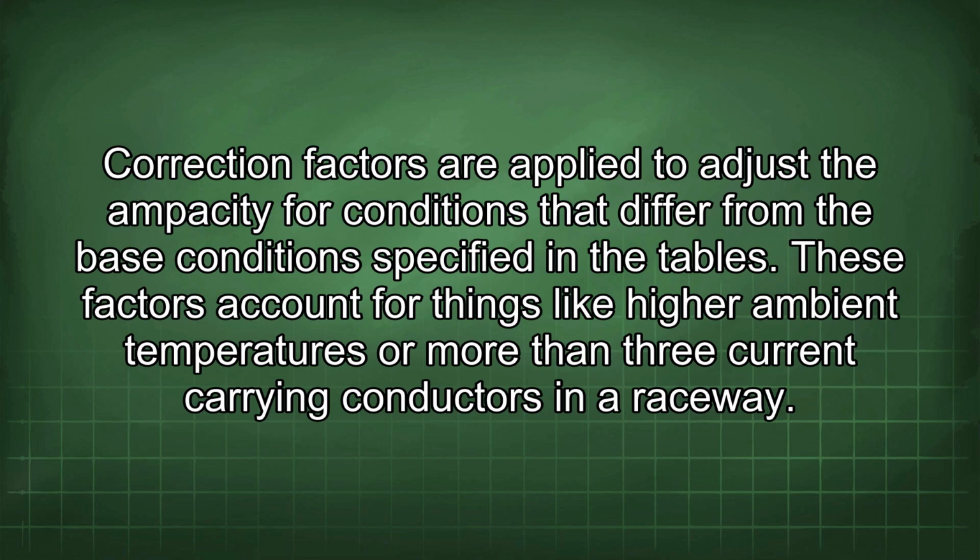Correction factors are applied to adjust the ampacity for conditions that differ from the base conditions specified in the tables. These factors account for things like higher ambient temperatures or more than 3 current-carrying conductors in a raceway.